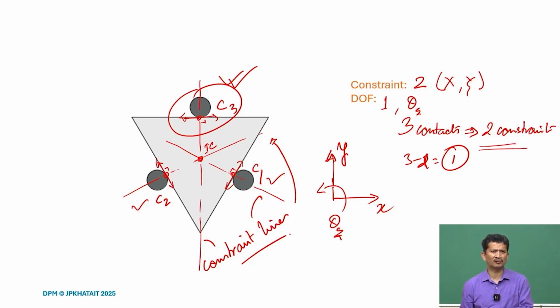Yes, many times we can say okay, it will be averaged out, but in that case we have to know a lot of things. We need to control other parameters, we need to control the dimensions well, and that is why it is very important to know if there is any over constraint and what the implications will be. So, this design is an over constraint design.